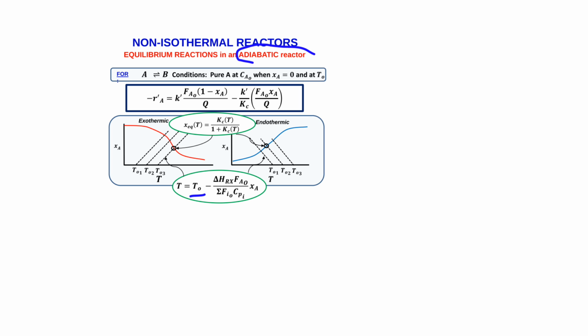If I'm now interested in solving this specific limit, so I have a given inlet condition, I've got an adiabatic reactor, and I want to determine this maximum X equilibrium, temperature equilibrium combination. Of course, I've got two unknowns. I've got temperature and I've got conversion, but I also have the equation that describes this line that I previously derived. So there is my X and temperature hidden here in my Van 't Hoff equation, but I can reduce it to a two unknowns, two equations kind of problem that I can easily solve using fsolve.